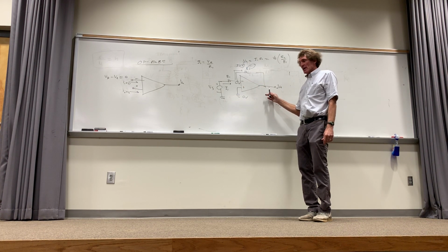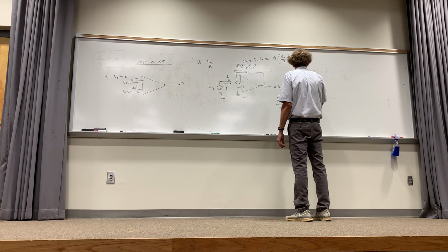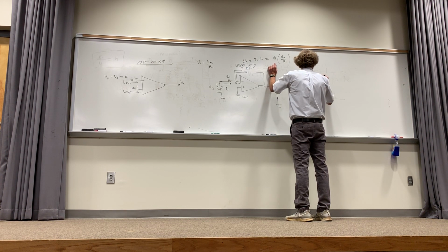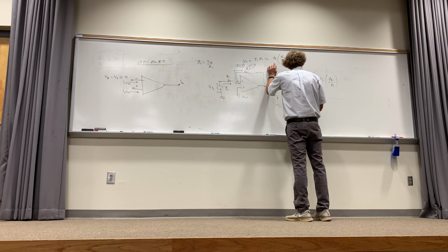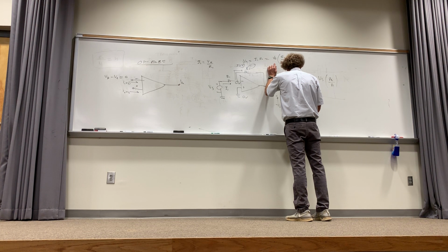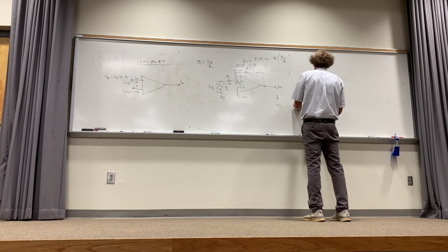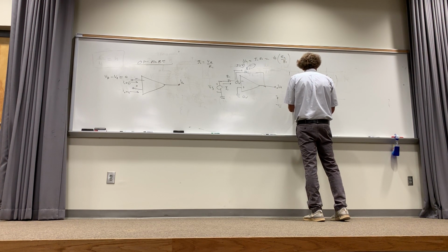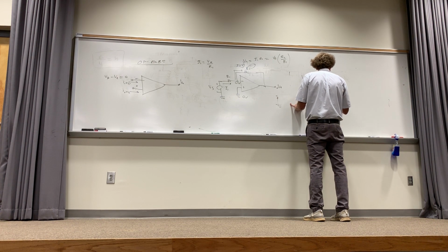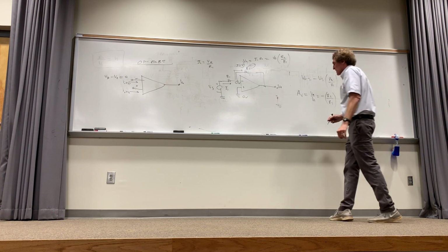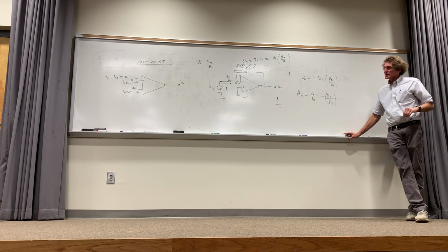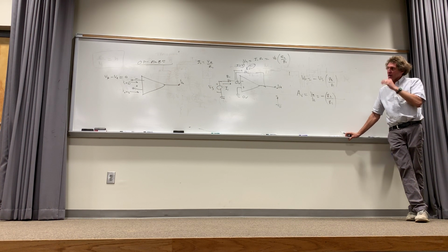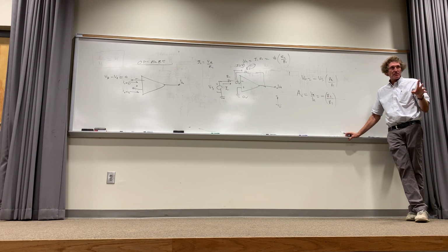Do y'all see that? So that means V out is equal to minus Vs times R2 over R1. We call this the amplification factor of the voltage, or AV, equal to V out over Vs, and here it's minus R2 over R1. Now, remember, these are AC signals going into that. Typically it's a time-varying signal that goes in between the plus and minus, so Vs would be plus or minus some voltage. Are you with me?